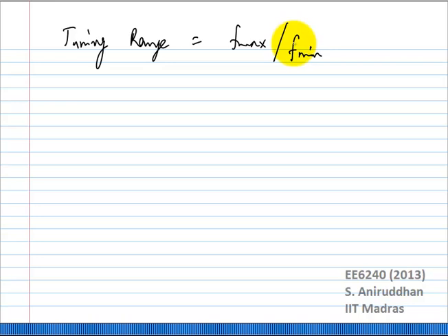Correct? In fact, if LO was 50 megahertz, if my VCO was twice that frequency, and that is common, right? Twice and 4 times is common, then if it is twice, the VCO frequency has to be 100 megahertz tuning range, not just 50 megahertz. Agree? Okay. Now let us take the case of, let's say a modern cell phone, right?